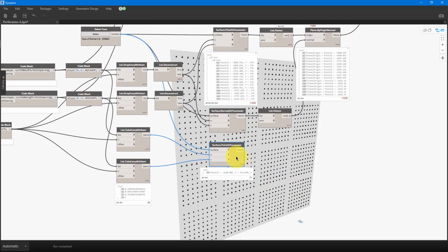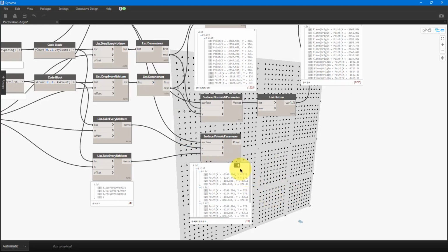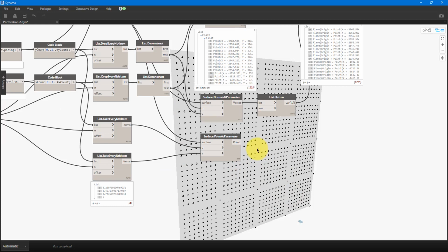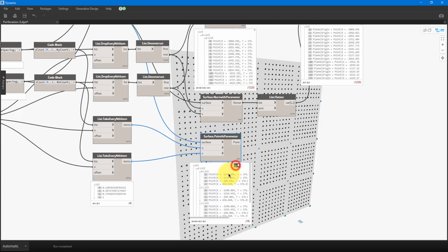That's only one value again, so we have to change the lacing here one more time to cross product. And now that gives you 16 points. Next step, I can turn these points, because they are already in groups of 4, into rectangular boundaries. There are different ways to do this, but the easiest way is to use a custom package called Springs.